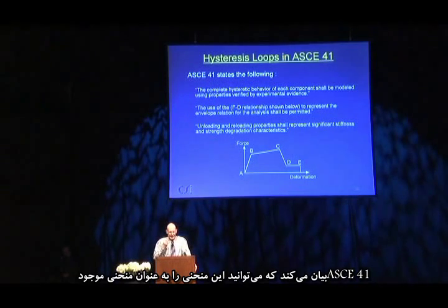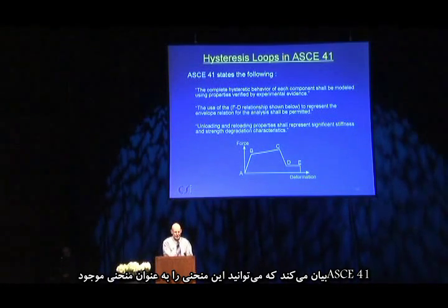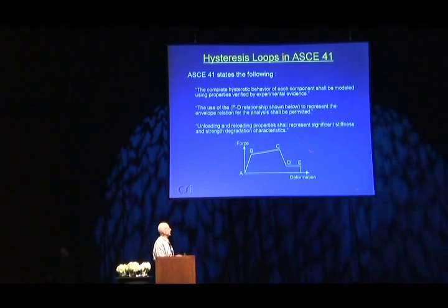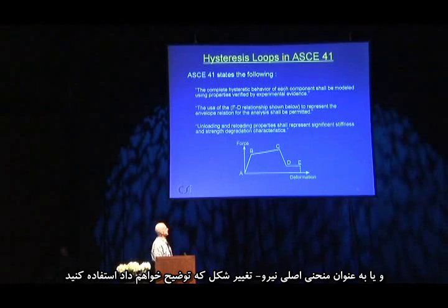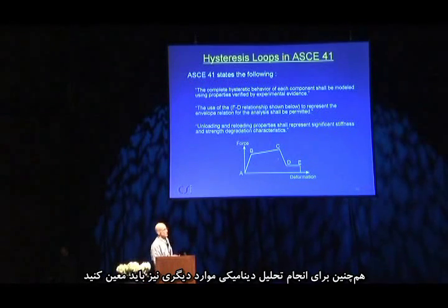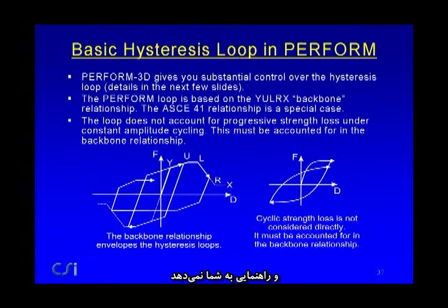ASCE 41 is saying that you can use this curve as the bounding curve or the backbone curve, which I'll explain again in just a moment, but there are certain other things that you should do if you're going to do a dynamic analysis. And it doesn't give you any guidance on this. You have to use your judgment and/or available experimental results.